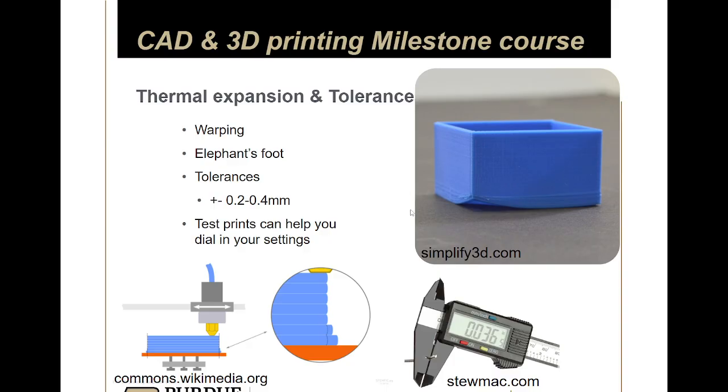On the bottom faces or vertical faces, you want to use chamfers, but on all these horizontal outer perimeters or edges here, you can use fillets, right? If you add a fillet, it'll spread that stress out over a larger area. So the forces won't be super high at certain points, and it's less prone to curling in this manner. Sometimes it's difficult, especially when you have really, really long prints, right?